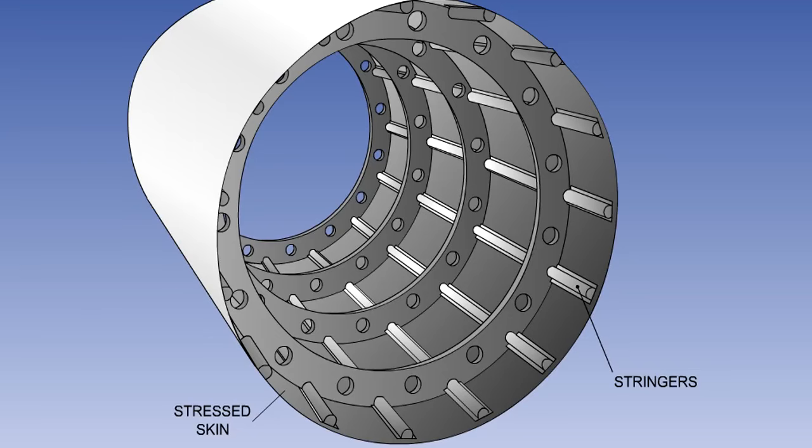Stringers stiffen the skin and assist the sheet materials to carry loads along their length. On pressurized aircraft, they take some of the strain caused by the pressurization and convert it into tensile stress. Longerons are more substantial than stringers and are fitted where extra strength is needed, such as for the seat rails in passenger aircraft.